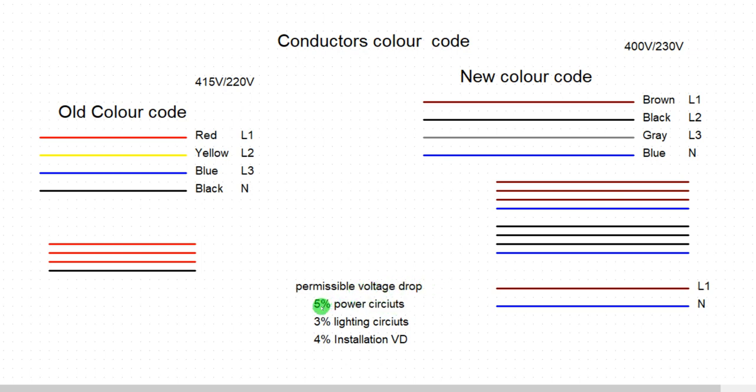We have 5% for power circuit, we have 3% for lighting circuit, then we have 4% for your installation, your setup, your entire system installation.